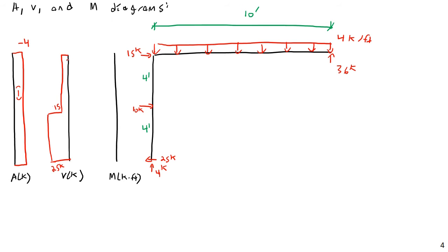And then it's going to go down to 0 because of the end force here. Then, to get this, this would just be positive shear throughout, although, especially when you start having things that aren't oriented horizontally, the definition of positive or negative shear really comes down to your sign convention.